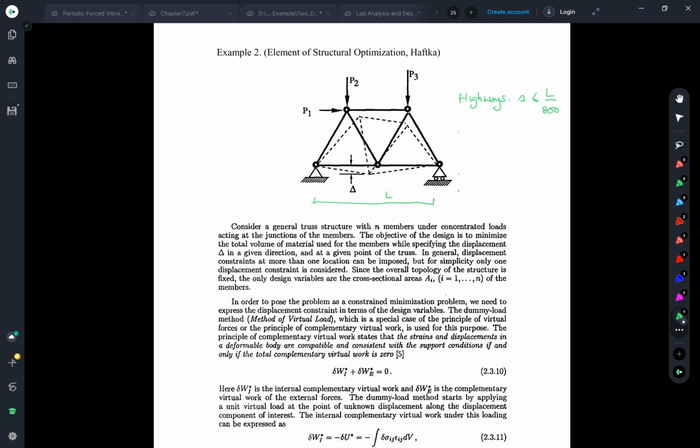I would like to briefly show you what the problems related to the real application are. The second case is if I have pedestrians, like we have a pedestrian walkway on the bridge as well. Not only the trucks and cars will cross, but we also have people who walk on the bridge. Then we are talking about the deflection limit of delta less than maybe L over 800. This is the example for the highway problems.